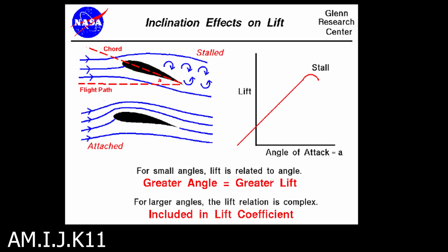High angles of attack or increased speed can move this transition point forward, leading to increased drag due to skin friction. As the boundary layer thickens and turbulence increases, there comes a point where the airflow breaks away from the wing's surface, causing a stall.